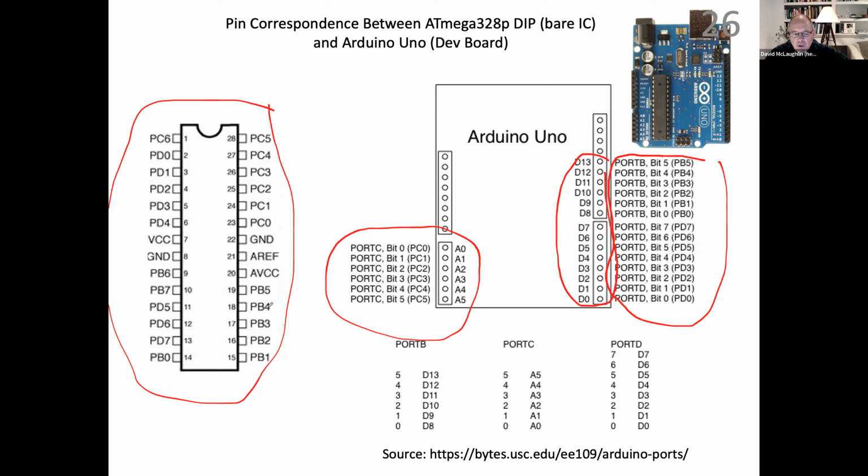Let's suppose we want to put an LED on PB5. Okay, I put an LED on there. All right, and I need a resistor there, and then a ground, right? Well, it was a terrible drawing. But if I wanted to do the same thing with the Arduino Uno, I would connect it to this pin over here.